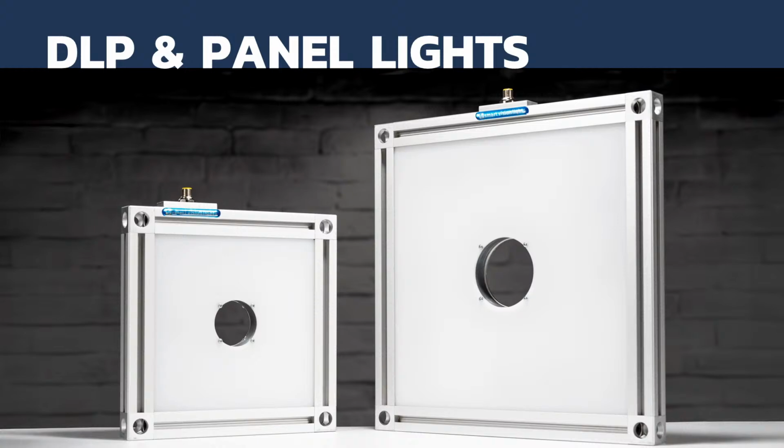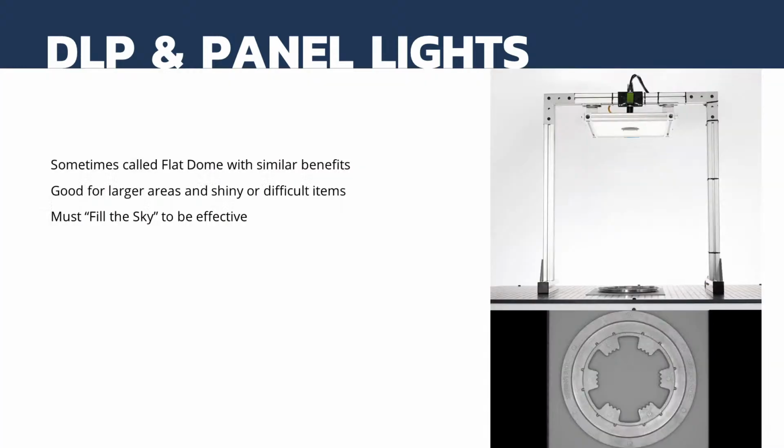Okay, next up we want to talk about DLP or diffuse light panels, otherwise known as panel lights. These are kind of like what a lot of you may know as a backlight, but a DLP or a panel light is meant to project light forward. So a DLP starts acting like a large ring light, and you heard me talk about the ring light needing to cover the whole area or field of view. So when the ring lights get too large and we need to cover a large field of view and still want a very direct lighting effect, we tend to use the panel lights to create bigger and bigger areas instead of trying to create humongous ring lights over the area.